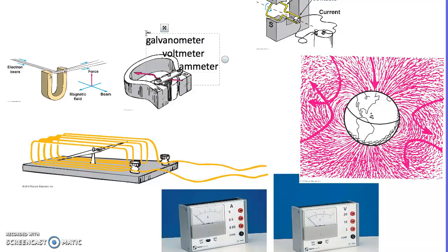However, most of what we will use in this class, and what most electricians will be using, is what we call a multimeter. The multimeter is usually digital, and you can have a knob on it. We'll use that later, where you can switch it to a certain range of amps, maybe milliamps if you're measuring small amounts, amps if you're measuring larger amounts, voltage, and also resistance.